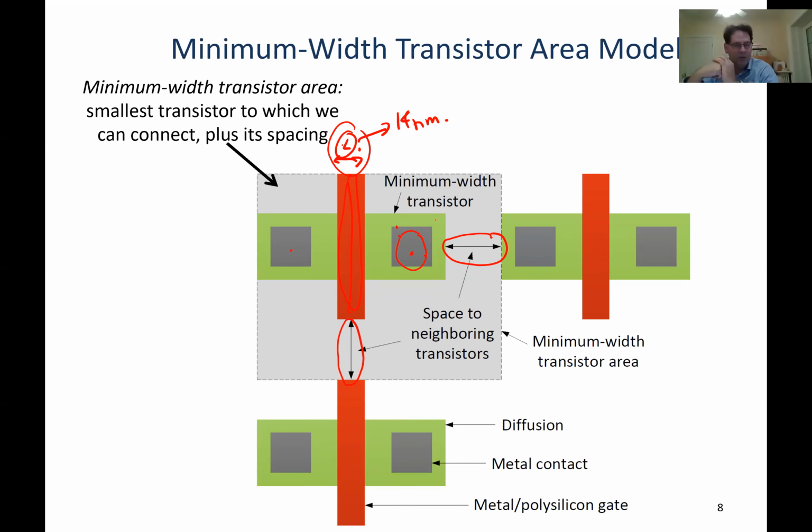For example, TSMC's 7 nanometers is generally believed to be comparable to Intel's 10, based on the way they count. But the basic answer is that it corresponds to the smallest gate length. On top of that, you layer some marketing claims, and everybody would like to have a small number because it looks good. Does that make sense?